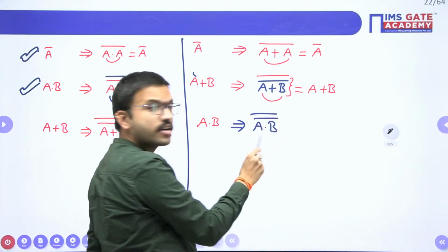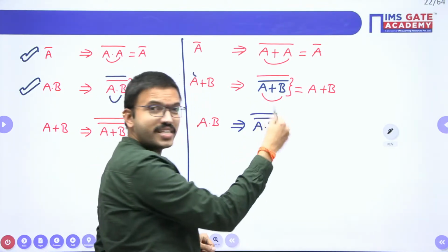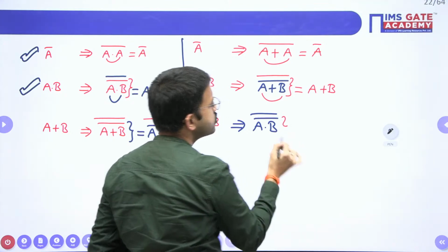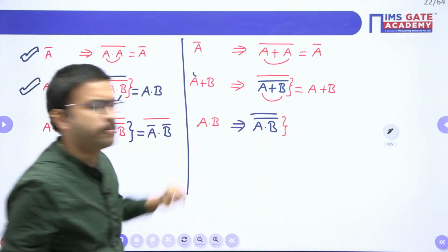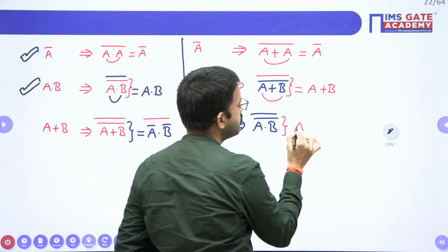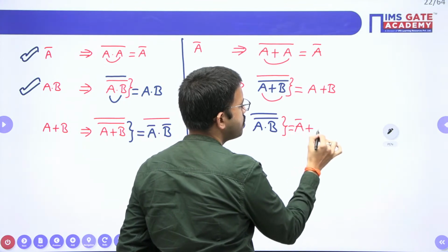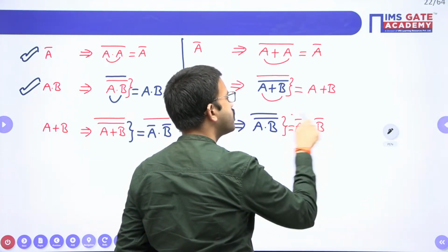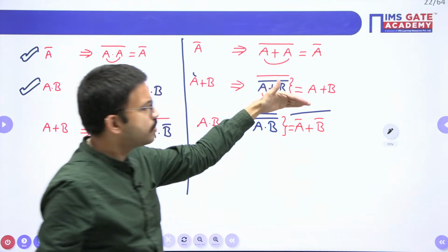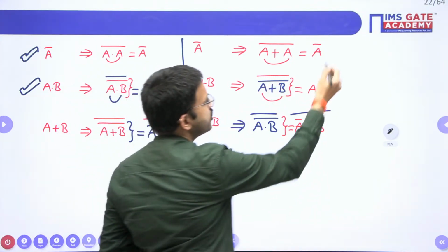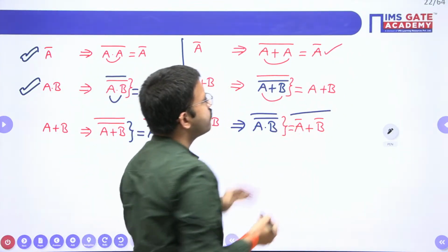But here you don't have a logical OR operation. In order to bring in a logical OR operation, we use De Morgan's law for the inner complement. So (AB) bar is nothing but A bar plus B bar, and keep the external complement as it is. Now, we have just told that A bar you can implement with the help of one NOR-based inverter.